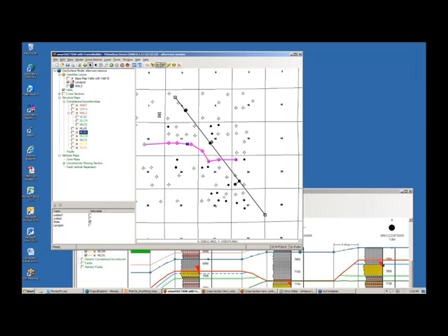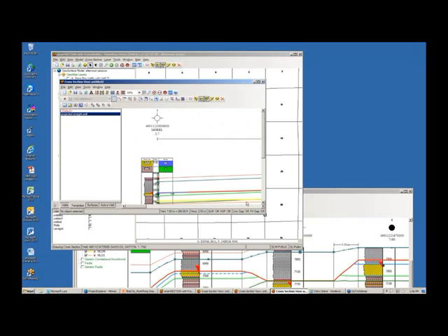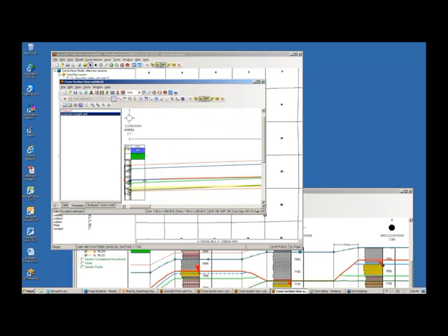The only thing you'll be able to grab will be the wells. Right, so I'll just come in here, see I have a wells layer that's made by smartSECTION, nothing to do with Geo Atlas. I can do define well to well and just quickly grab those, double click, cross-section opens, apply my template, and boom, you're off and running.